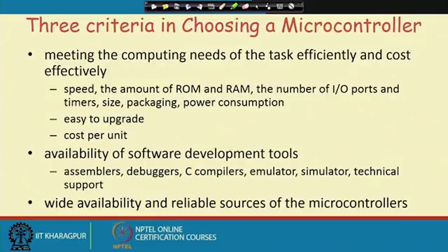So, they all will contribute to the choice of the microcontroller. The second important thing is upgradation. Today we are using some microcontroller; tomorrow can we go to the next higher microcontroller in my system? As a result, the system performance will be enhanced, but at the same time I do not want to change the hardware too much. So, the pin configuration and software compatibility should be there.